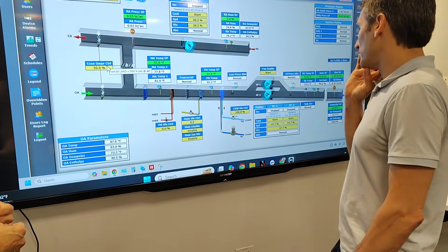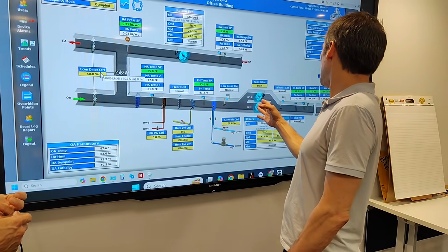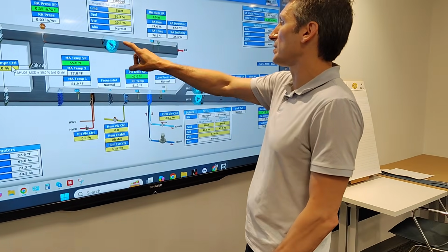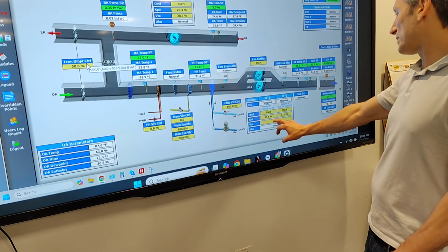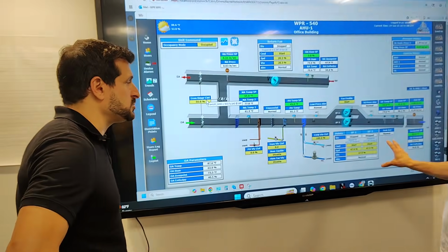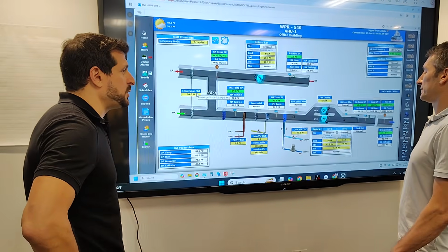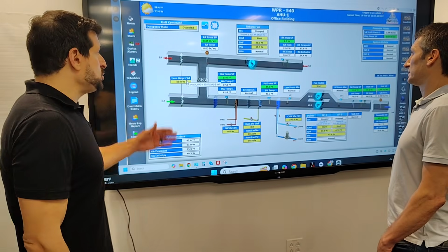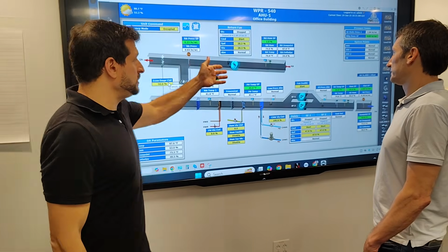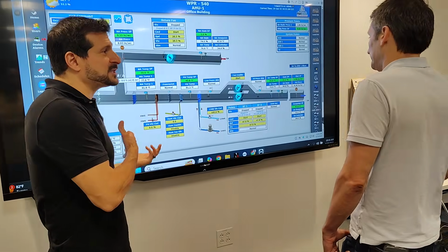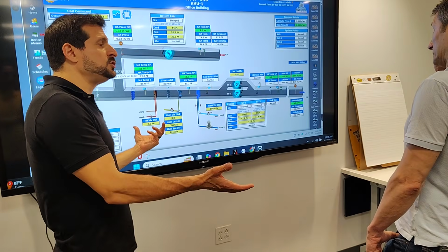So if we were to do it correctly, we would say supply fan, I don't know, at what set point would we set it so that it could be equal? You have to measure. There's no answer to that question. Right? So the answer to that question comes from the design part, or at least in the initial setup part. You'd have to come over here and take pressures, find out what your fans are delivering in order to calculate that out. And then that's why that stuff is programmed. That stuff is not user adjustable.